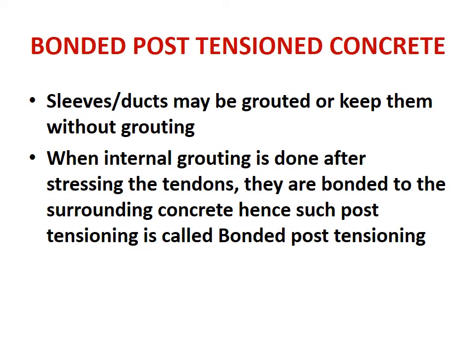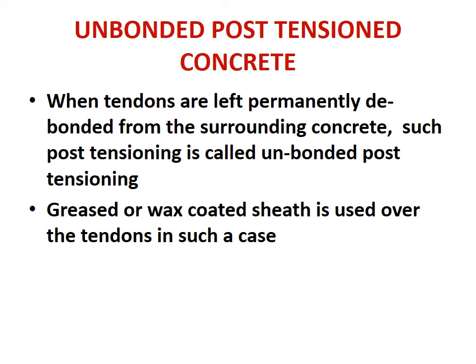Now there may be two cases: these sleeves or ducts may be grouted from inside, or they are kept without grouting. When internal grouting is done in the sleeves or ducts after stressing the tendons, they are called bonded, because they get bonded to the surrounding concrete. So such post tensioning is called bonded post tensioning. And in case tendons are left permanently debonded from the surrounding concrete, such post tensioning is called unbonded.